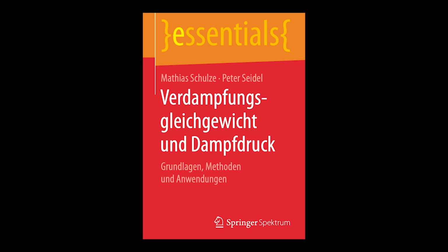Precisely. This creates a nearly perfect vacuum within the entire low-pressure circuit, establishing a massive pressure differential that the turbine operates across. That maximum pressure drop means the steam exerts maximum force over the maximum distance, directly increasing the mechanical work extracted and, consequently, the efficiency. So if a condenser failed to create that vacuum, efficiency would just plummet.